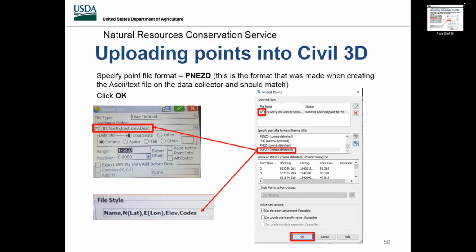Okay. And I'm just going to look through these chats real quick. There was a question about finding discrepancies between LiDAR elevations and GPS collected elevations, and which one to use. That's a great question. It all depends on when the LiDAR was taken. I know a few months ago, probably longer than that, the Russian satellites kind of were taking on some kind of hit, and we were getting some inaccurate GPS elevations. So if you did a survey in a certain time period, and I don't know exactly what that time period was, we've had some elevation discrepancies based off of LiDAR.